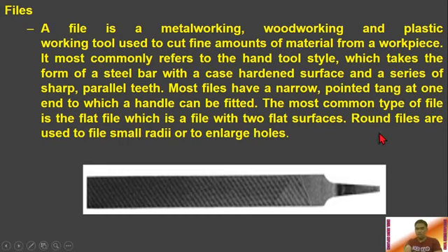So the round file, we have also another type which is the round file, used to file small holes or to enlarge holes. The main purpose of a file in electrical works is to file the end of our conduit, so that the covering of the wire could not be stripped once we put our wire inside the conduit.